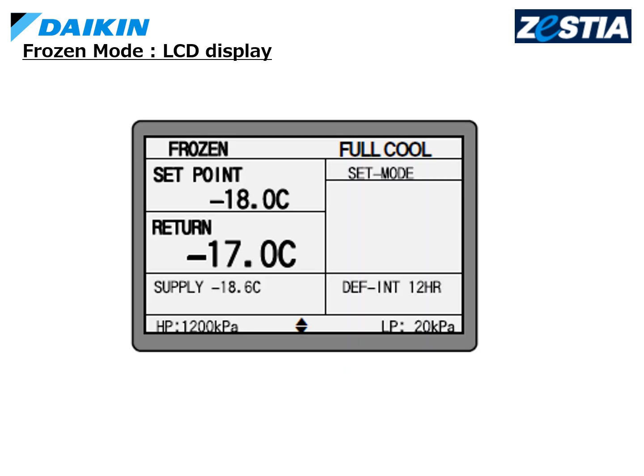This section describes the LCD panel display in the frozen mode. Frozen is shown here, and the current operation mode is shown here. In this screen, full cool is shown. It shows the return air temperature, which is the control temperature.